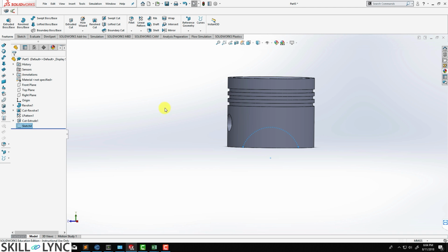Now we are going to select the shape and we are going to make an extruded cut. So let's click on that, and we want to basically cut on both sides, so we can just use through all both, and that's just going to cut on both the sides. While using this cut option you need to be a bit careful, because you see that the flip side direction is selected to outside.